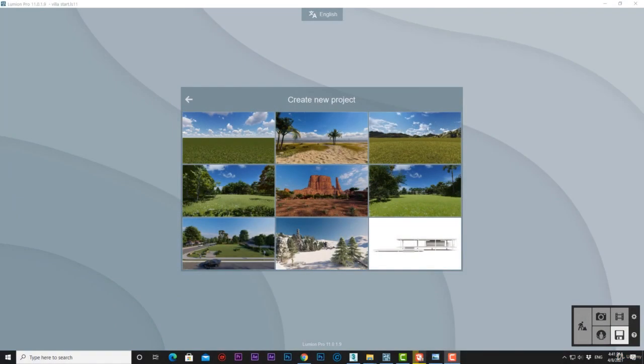A new feature that comes with Lumion 10 and above is that now we can import Max files directly without the need to export to FBX. But to use this feature, 3ds Max must be installed on the computer you are using, as Lumion will use that to create its own FBX file in the background.